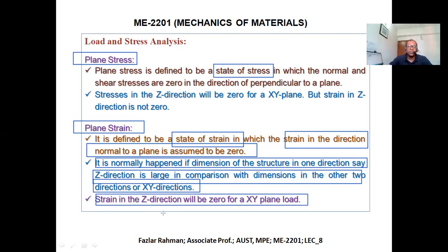For example, say you have a pipeline from Dhaka to Kumilla. You know, we study pressure vessels, right? In a pressure vessel, what type of stress is working? Longitudinal stress, sigma L, right? One is sigma L, the other one is tangential stress. What is sigma L? Sigma L tries to split the pipe into 2 parts. That means they try to pull it like that.